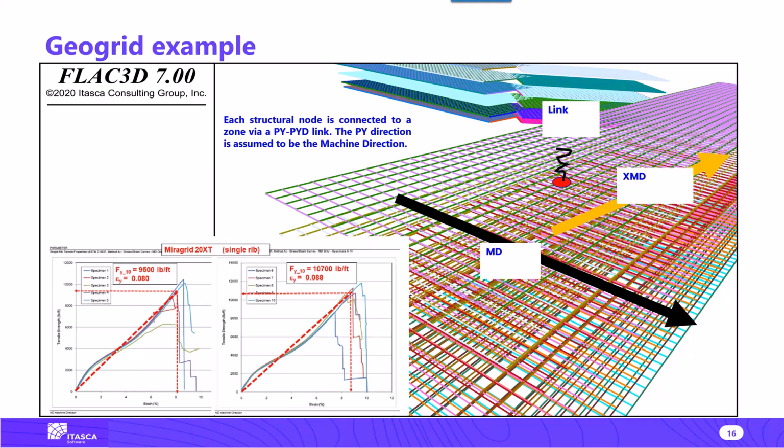So in many cases, especially when we adopt simplified analysis, we apply the full force available for the geogrid in our simplified analysis, without realizing that the force that becomes available at 1 or 2% strain, which would be compatible with a service limit state for the structure, is much, much less. And then you see a loss of performance or other issues because this contrast in terms of stiffness and strain compatibility is not adequately considered.